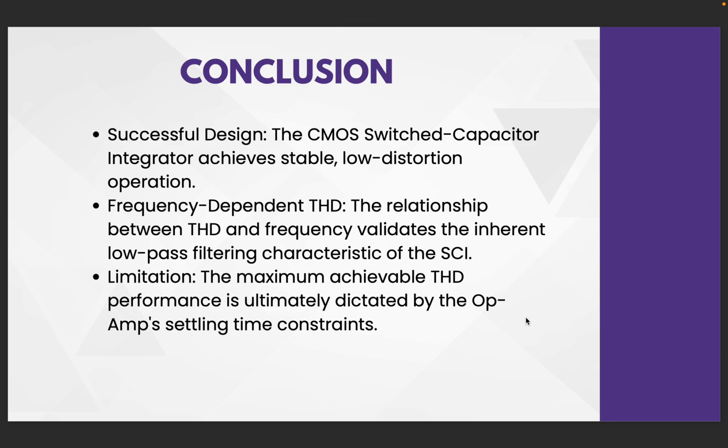Conclusion. In conclusion, our CMOS-based switched capacitor integrator design successfully achieves stable operation with very low distortion. The observed frequency dependent THD relationship validates the low pass filtering nature of the circuit, while the design performs efficiently across low and mid frequency ranges. Its high frequency performance is limited by op-amp settling and switching parasitics. This confirms the importance of optimizing op-amp dynamics to further improve overall linearity and distortion performance. Next slide.